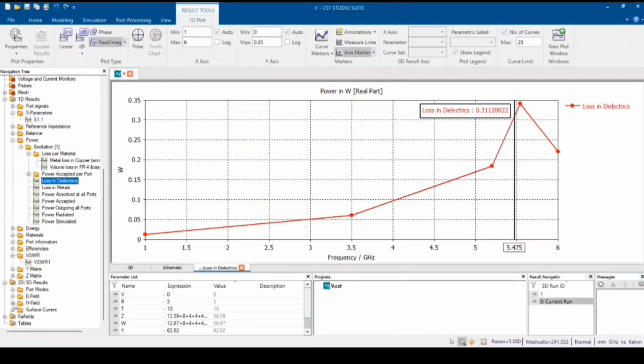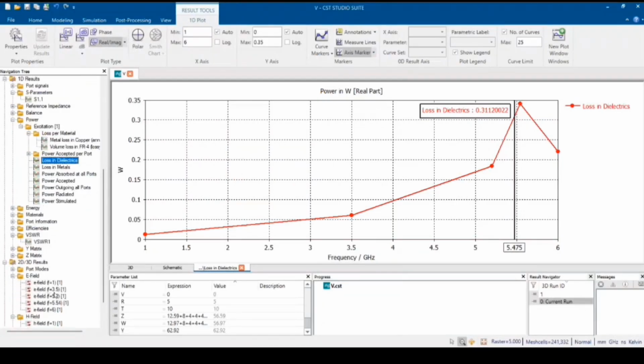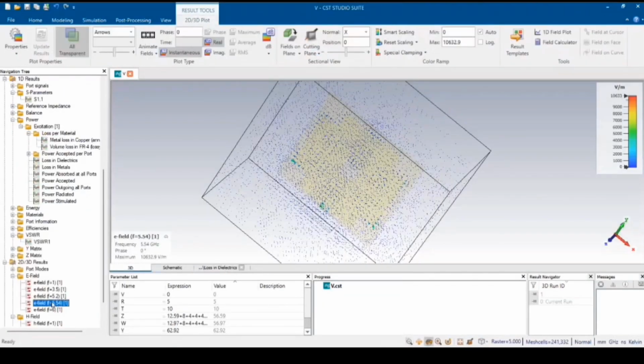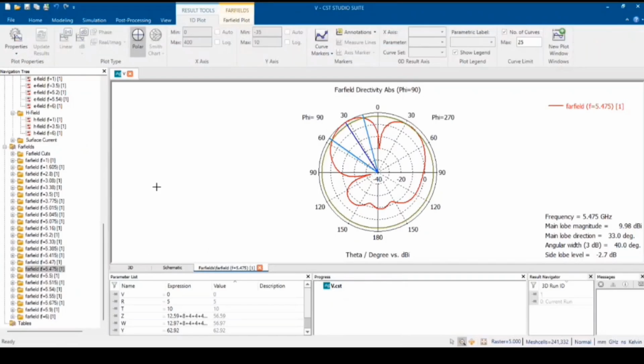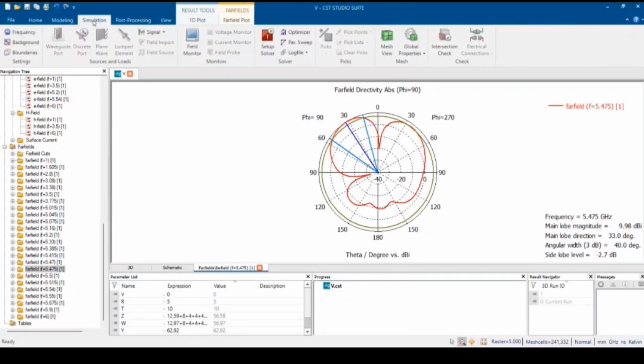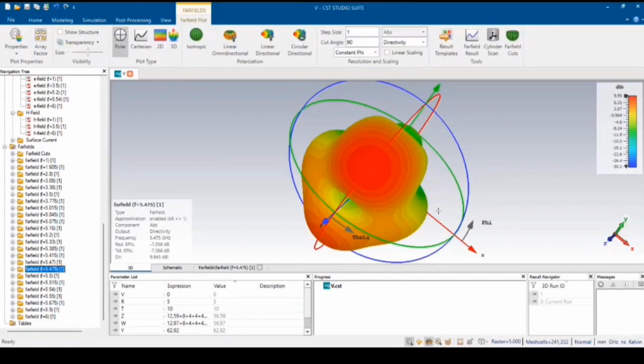transferred to the antenna. Then the given graph displays the voltage standing wave ratio of the microstrip patch antenna between the 1 GHz to 6 GHz range. As a rule of thumb, VSWR is regarded as one of the important metrics in an antenna system as it analyzes the impedance matching ratio between the antenna and transmission line. This fluctuation indicates resonant frequencies where the power acceptance is greater, probably because of interaction with the simulated system or phantom model. The peaks are at 1.5 GHz, 3 GHz and 4.5 GHz, showing frequencies at which maximum power is being absorbed.